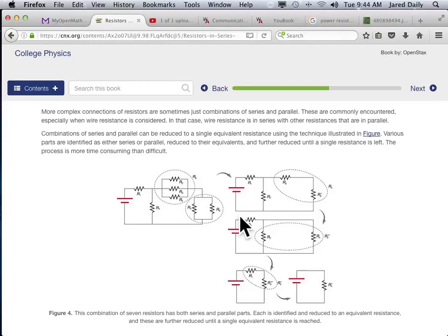And then all of a sudden, this first resistor is in series with that resistor that represents every other resistor in the circuit, right? This resistor now represents these 2, and these 2, and these 2, and these 3, and everything else. Add those together, and you have the total resistance of this circuit. This resistor represents the total overall resistance of this circuit.